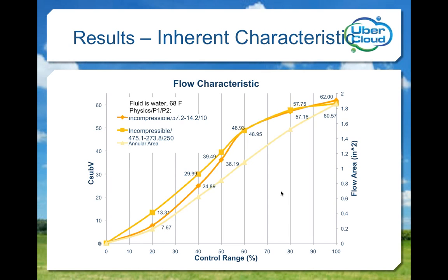While 11 control positions are ideal to fully map the characteristic, 5%, 10%, 20%, and so on, I ran just 6 design studies to find out if virtual valve testing is a viable way to verify a valve design. This was simple. Change the position of the trim in Inventor, activate CFD, and tell the program that this is a new design study with the same settings as another design study. All this takes just a few minutes for each control position.